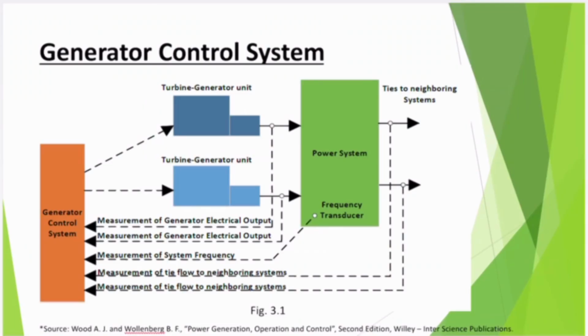So now what is happening? The electrical energy requirement keeps on oscillating. We cannot make it constant because it is impossible, as it depends on many customers' behavior. However, the mechanical energy input that we provide to generate electricity needs to be controlled as per the variation seen in my electrical energy requirement. So that is the challenge.